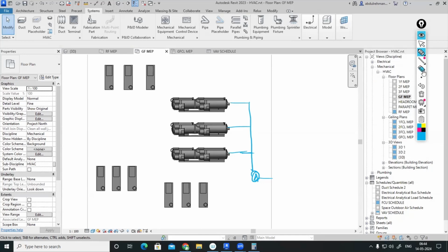The next option we can go for is manifold pump. Manifold pump means, for example, 1 or 2 pumps we will be having there. From the chiller return, it will be taking it. And after that, it's a header. Then it will be connecting to this one. It's not dedicated. 1 or 2 pump sets we will be arranging, like if it is beyond 5 HP, then duty standby. We will be arranging a duty standby arrangement. Accordingly, with respect to the demand, the pump will be working. That is called a manifold arrangement.